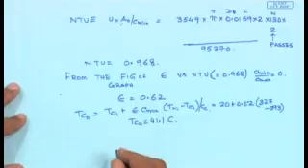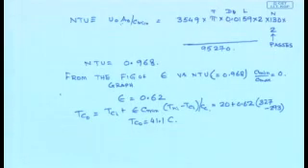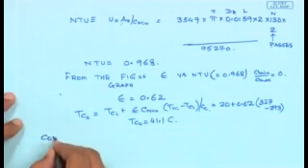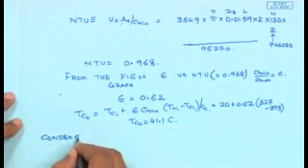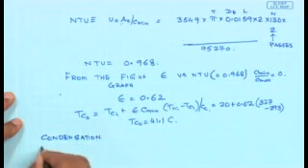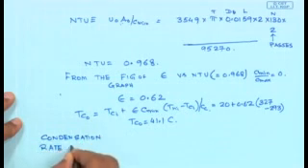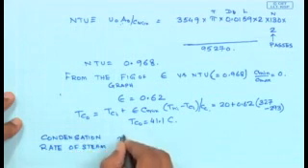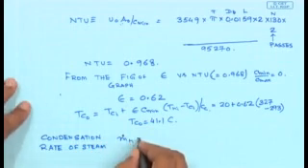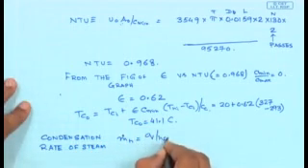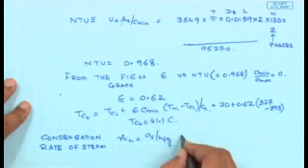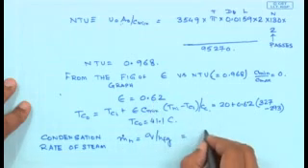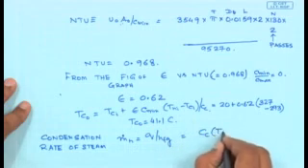The third part remaining is the condensation rate of the steam. So, let us do the last part over here. The condensation rate of the steam, m dot of the hot fluid, is simply Q by HFG, and since I know epsilon, everything is known to me.